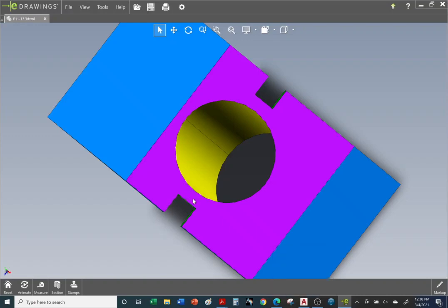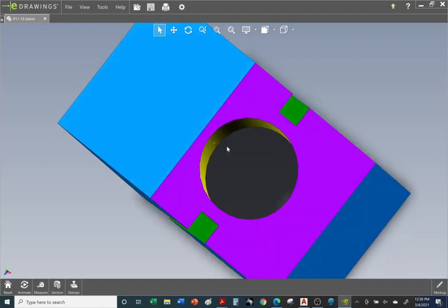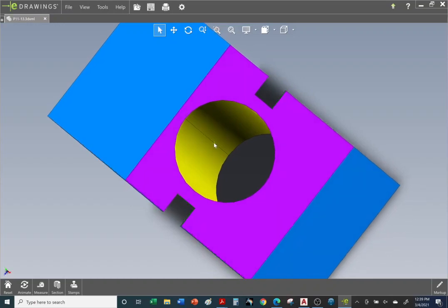Oh, before we do, keep in mind, we're looking down the rectangular slots. And notice how we don't see the exit completely for the hole because it's at a different angle. Okay, so the author, she chose to make this a little bit more difficult, right? More challenging. All right, so we'll be able to see part of the exit of the circular hole, so we're going to have to draw a red hidden line. We'll come back to this. Let's first do the periphery. So we'll draw the periphery of the auxiliary view.